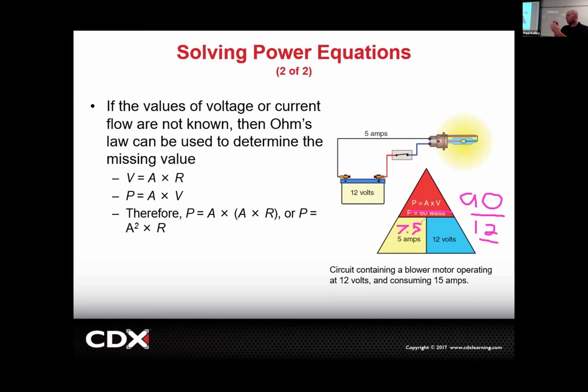And now with added amperage, a lot of times it can end up having a little resistance and get a little hotter there. So the more amps we're going to flow, the more resistance is actually going to make more heat. And so generally what we try to do from the repair side is just run the OEM equivalent.